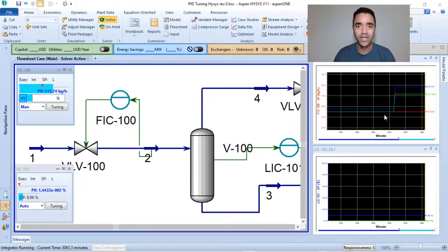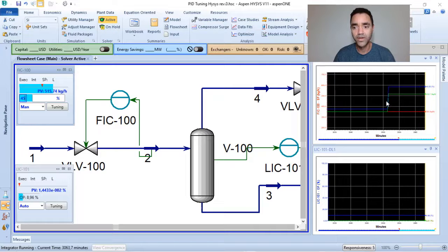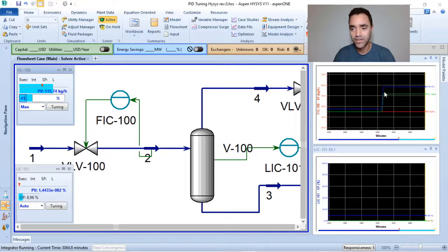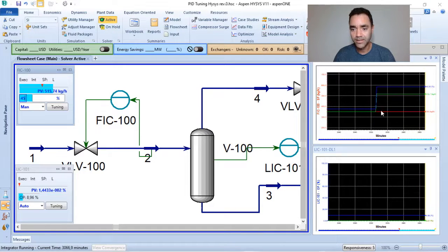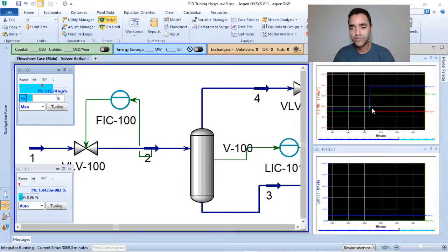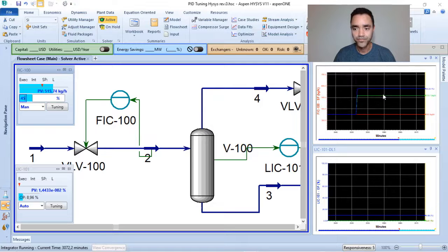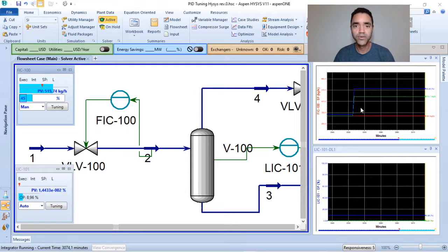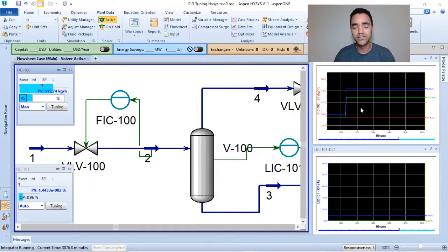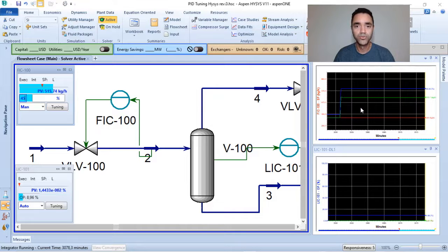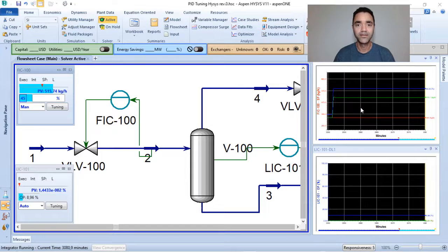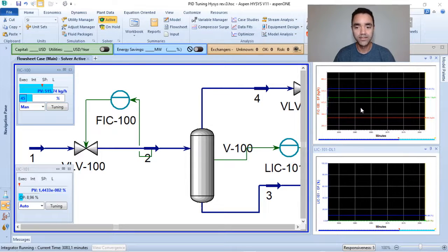I will look for the time constant and also for the gain of the process, because now the set point is not matching with the present value. So this is the way that Ziegler and Nichols recommend you to define the values for the PID.